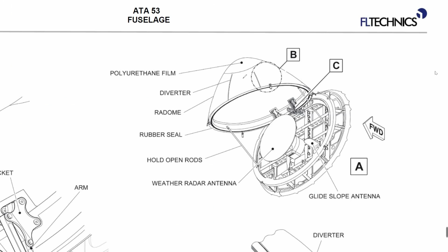Because they are accumulating charge, and the radome is also one of the most popular zones for lightning strikes. Usually lightning hits the radome and the leading edge of components, like the wing leading edge, the vertical or horizontal stabilizer leading edge, or the inlet of the engine, because once again, this is the zone where we have accumulated charge.